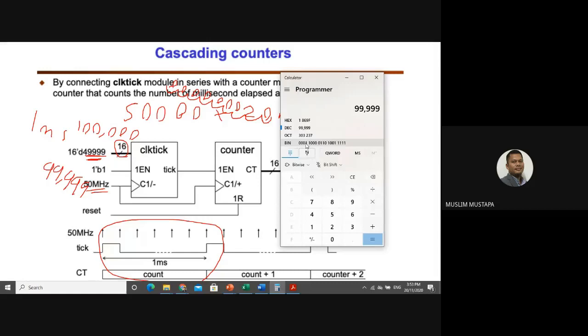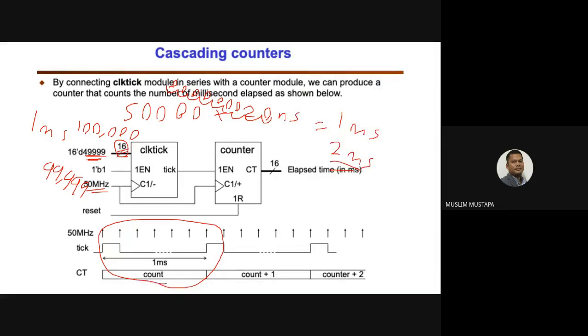So how many bits do we need? If you add 17 bits, you can see here 4, 8, 12, 16, and 1 here. So 17 bits. The size is not enough here, so you have to change the size too. This is just an example, maybe in the exam a question like this can come. If you want to set the counter tick every 3 milliseconds, we modify the circuit. Make sure you understand this part of the calculation.